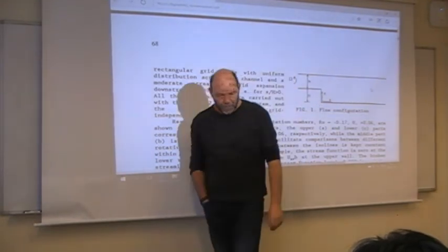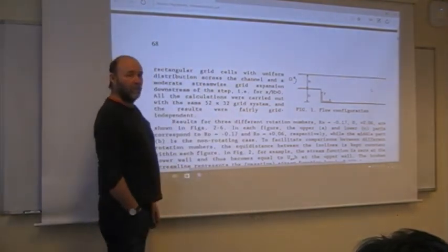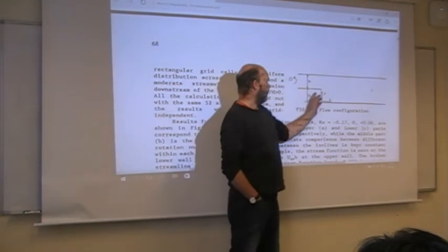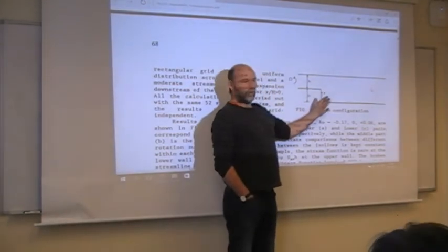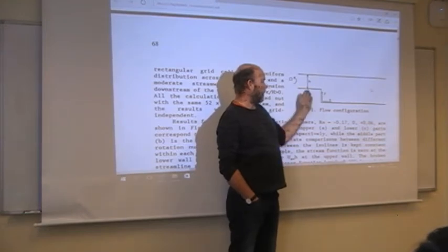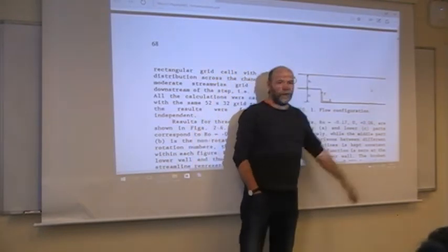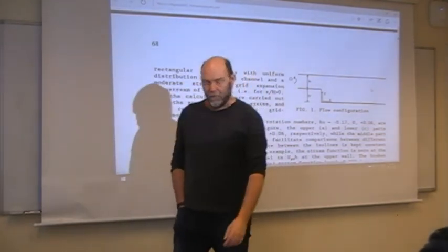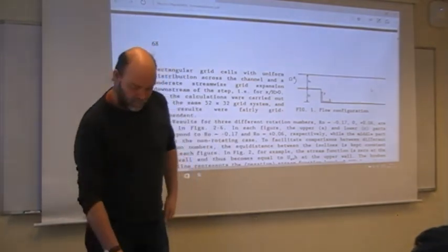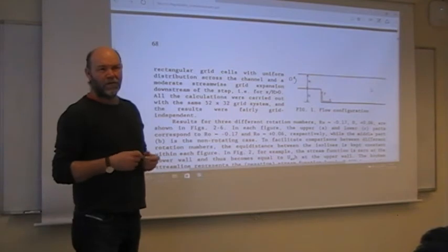Using k-epsilon, you can get any number from 1 to 20 step lengths, depending on your choice of models, wall models, and here the choice of mesh. If you change the mesh a little bit, you get a totally different answer every time. So the standard k-epsilon, not so funny always.